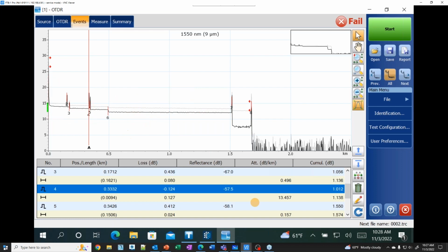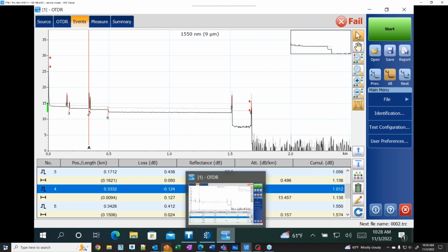So these are where the interpretation comes in. And now all of a sudden you start to understand, well, okay, the fiber fundamentals are a big part of the interpretation of running an OTDR. Because when I get to the setup, you'll see it's pretty easy. So that ties in kind of the fiber 101 stuff, right? Ties in understanding what causes attenuation and what some of the values should be and how to identify them on the event table. Now we need to get into some issues with the OTDR, which is basically kind of the OTDR theory portion of the presentation, right?